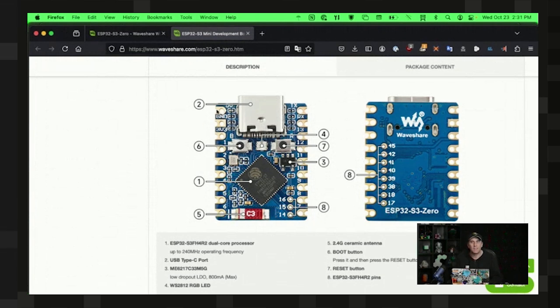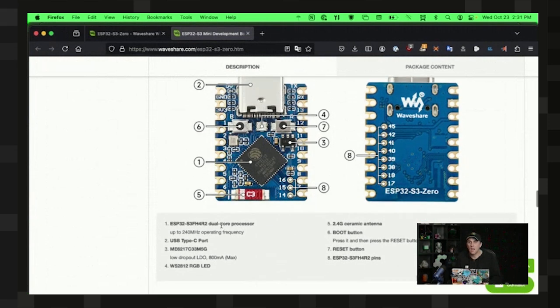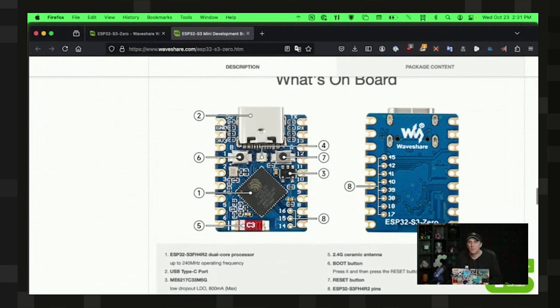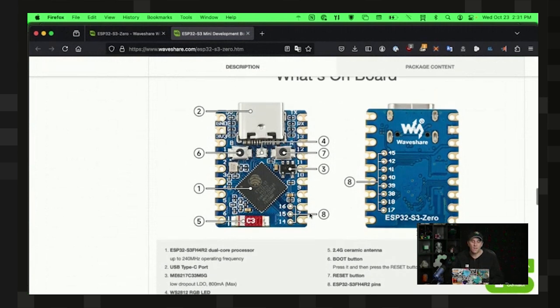Castellated means that it's basically like a through hole pin that goes all the way out to the side, has all this extra space for soldering, but it can also be done via through hole. Now, for the purposes of what I'm doing, I'm treating this as just a soldering pad. So it's going to be flat. I'm not going to be doing through hole. I'm going to be doing SMD instead. That's an important distinction because you kind of have to decide with these modules. And it's nice, though, to have the option.